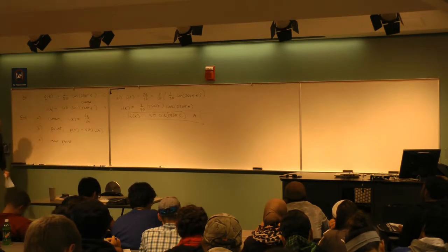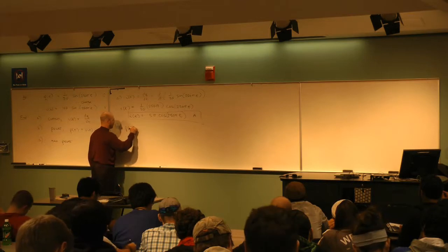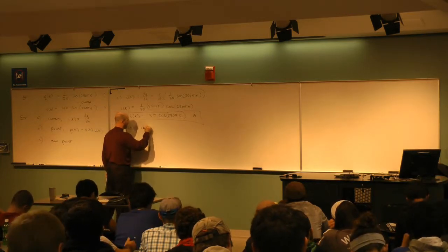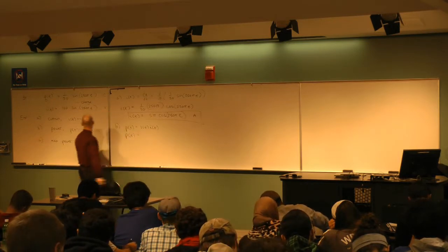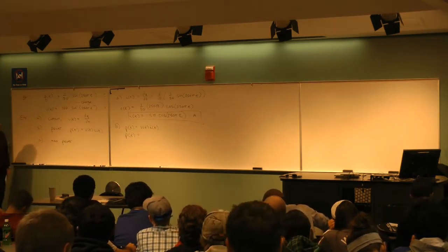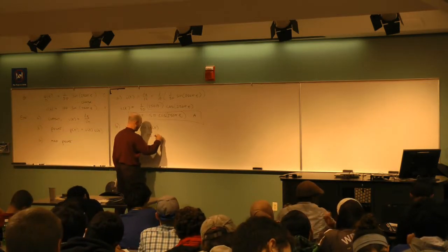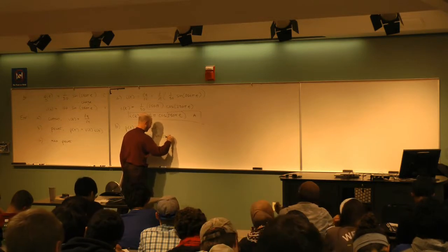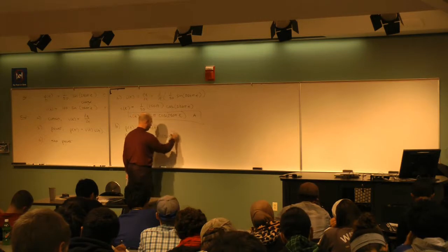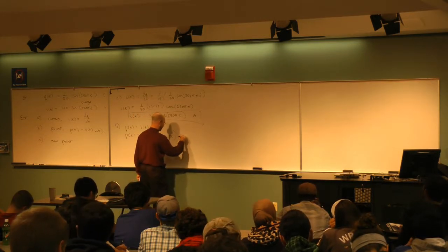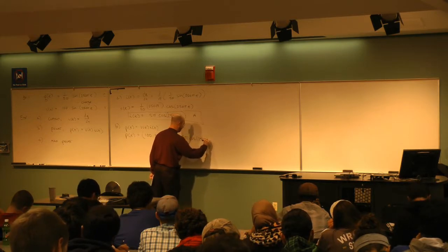All right, so part B. What is the power? V times I. So I want the power, P of t, voltage multiplied by current. That should be pretty straightforward since I've got both of these things now. The voltage is 100 times the sine, 250 pi t. And the current just calculated is 5 pi times the cosine 250 pi t.